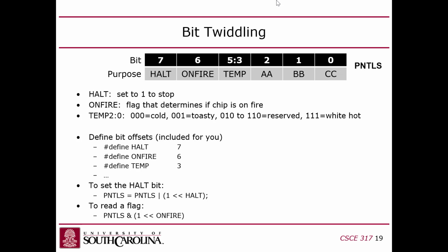You generally don't look at the individual bits of that integer. You just use it as a number, right? But when you access these control and status registers, you need to interpret specific bits for specific things, right? So how do you do that? Well, basically you use shift instructions and bitwise logic operations. I should say shift operations, because we're going to try to stay in C in this class. We're going to try to not have to go to assembly language. So when I say shift instructions, I really mean shift operations in C, right? Likewise, bitwise operations are also a concept in C and in Java as well, right?